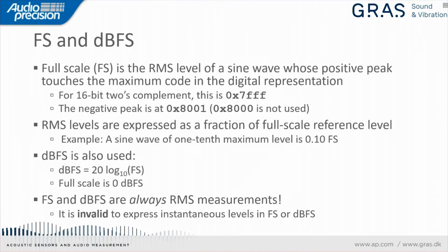So the definition of FS and dBFS actually comes from the Audio Engineering Society, which has a standard, AES17. What the standard says is full scale is the RMS level of a sine wave where the positive peak reaches the maximum digital code.